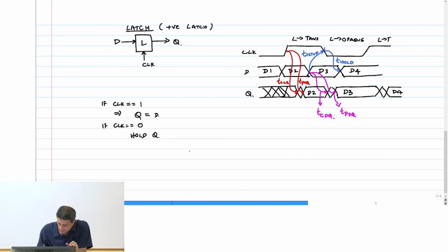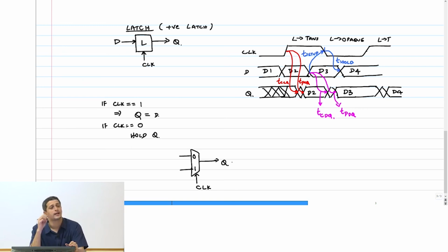Mux, right? A multiplexer. This is a clock. The select line is a clock. If it is 1, then this is 0, this is 1. This is Q. Where should I connect D? Yeah. What should I do on the other end? Simply feed it back like this. Okay.